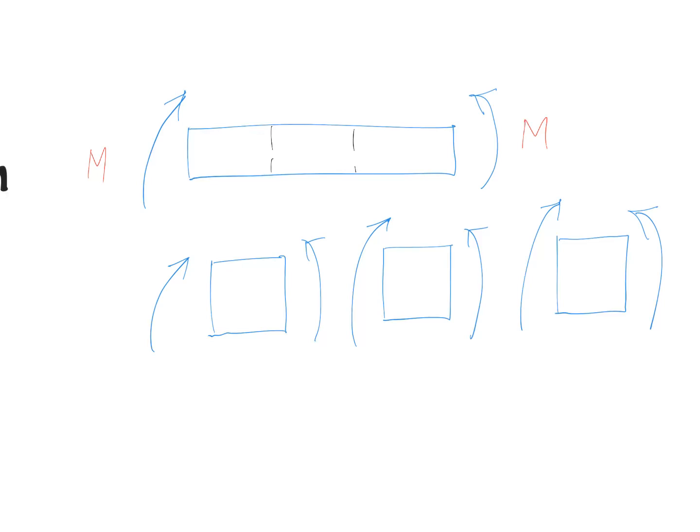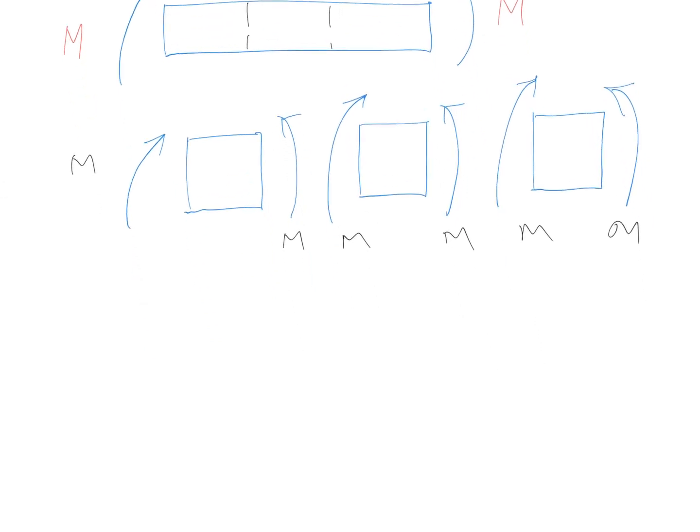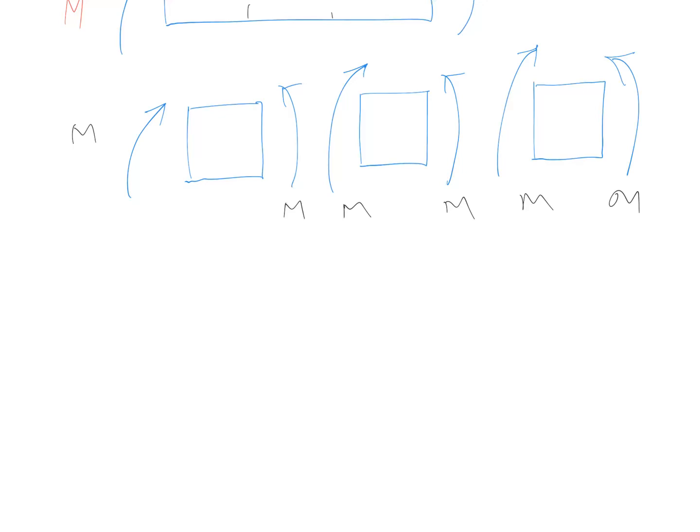Now the next thing is obviously to draw the free body diagram. So the 3 free body diagrams will be shown here like this, each with moment M on both faces. They are subjected to the same kind of loading. Let's say that instead of these sections remaining plane, they bulge out. It's a postulate; we need to prove that that won't happen. So instead of remaining plane, these faces are bulging out like this.